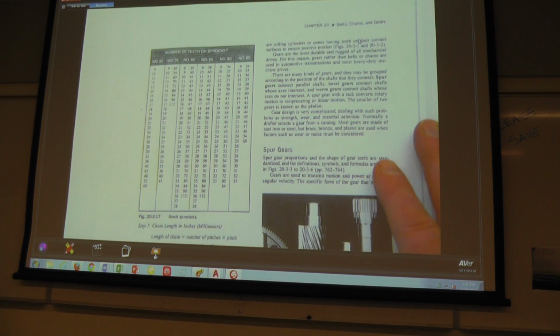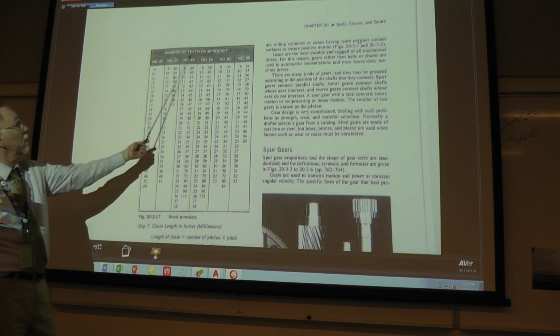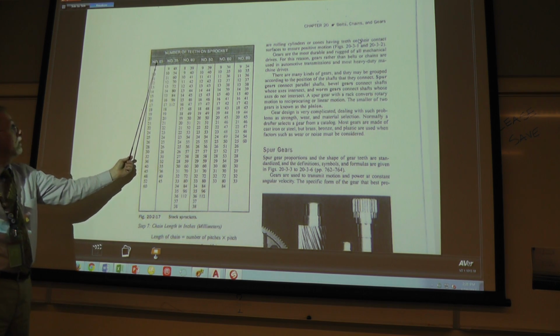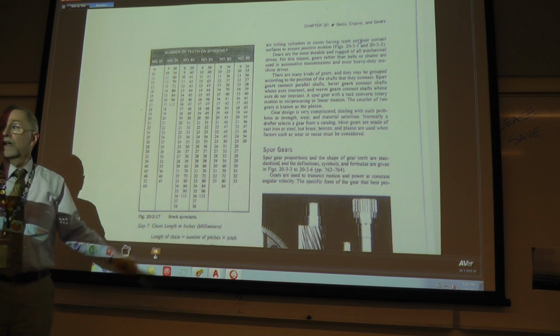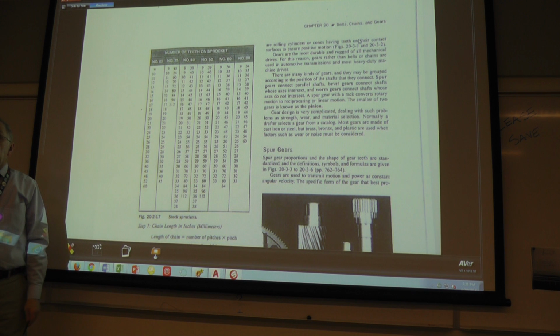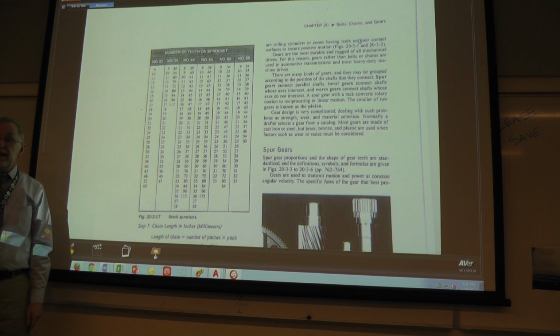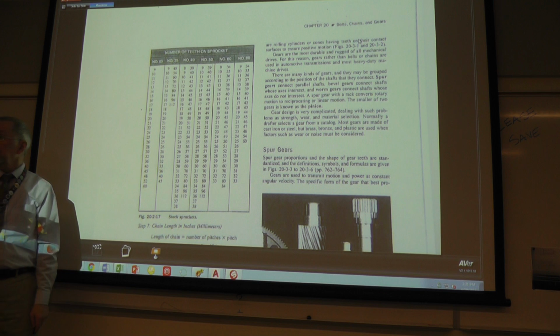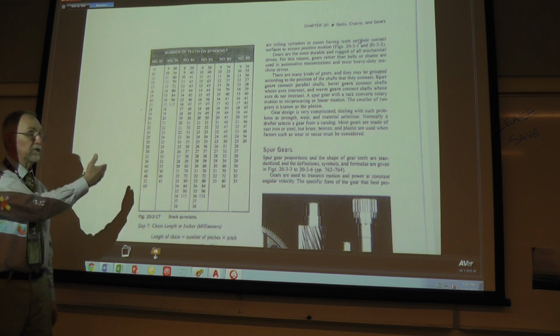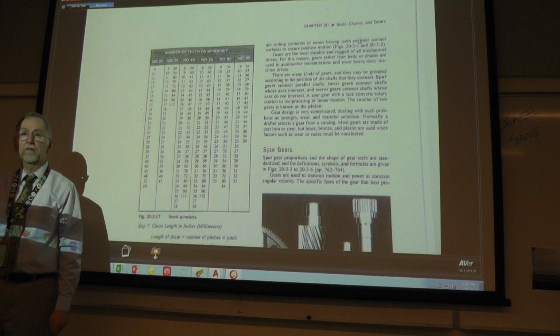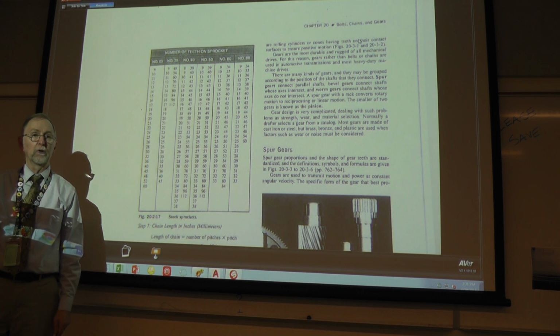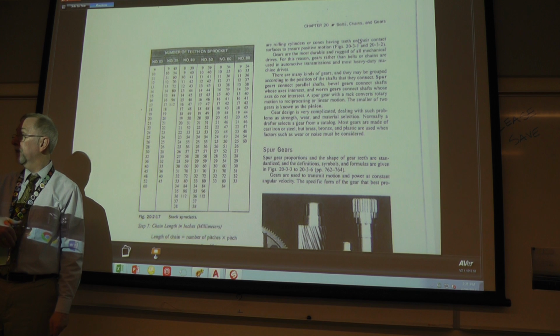And then on the last chart that we would be using on page 22, number of teeth on the sprocket. So it lists a 25, 35, 40, 50, 60, and 80 chain. It's to my advantage in a design situation that if I can go to a supplier that has these number of teeth already made, it's sitting on the shelf, I get a catalog number, I order it, and I can put it into my design.